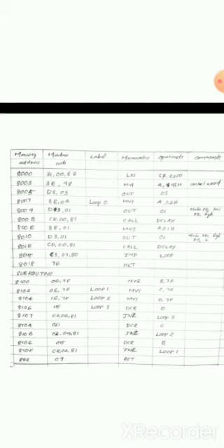Now PC4 and PC5 carry low voltage, so the red LED shines and the green LED doesn't shine. A suitably large number, FFFF, is loaded in the DE pair. This number depends on the required delay time. The delay subroutine starting from 0B is called.